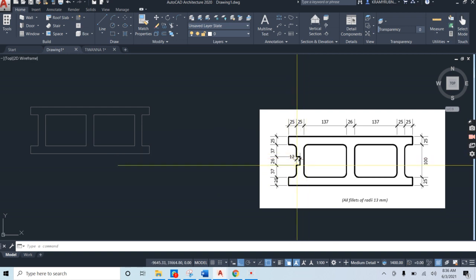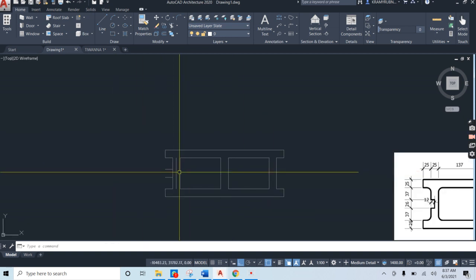Now we also realize that at this end there is to be a small indentation. Now it is given as 37 from both sides. Let us go offset 37 millimeters, and we are pretty much going to be offsetting from this line in this direction and from this line upwards. Now we have our two lines. There is also to be an offset of 12, and that is measured from this line going in this direction. Notice that our lines need to intersect or to connect.